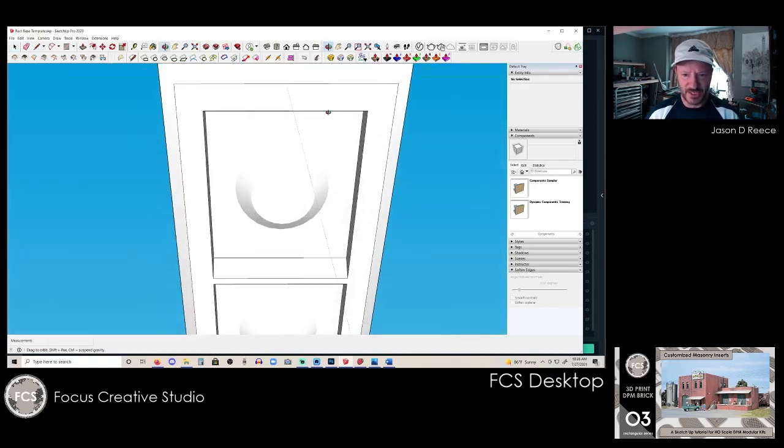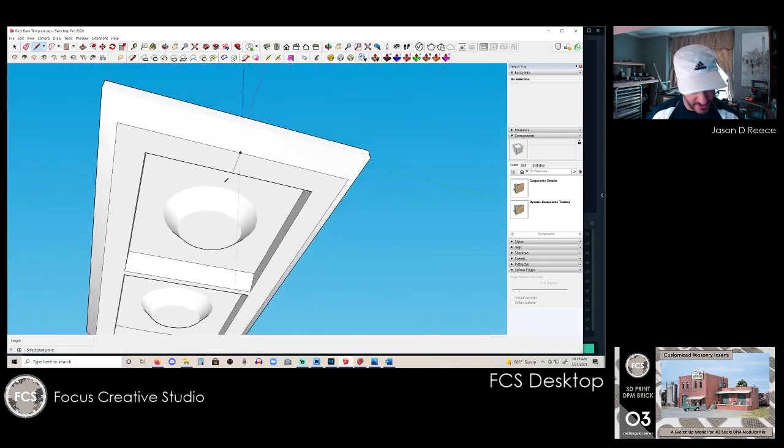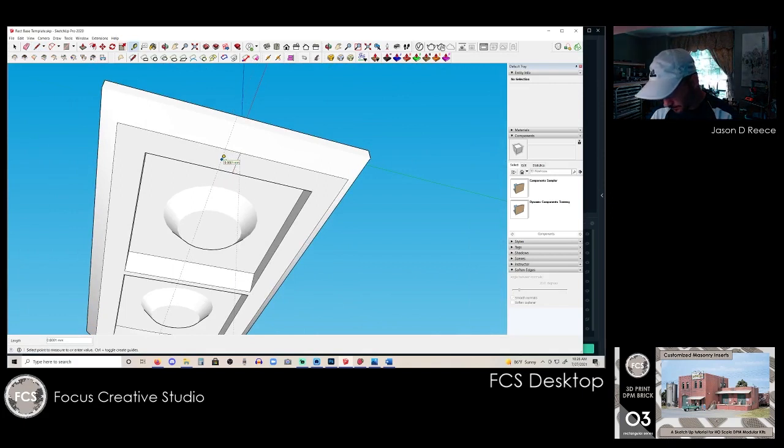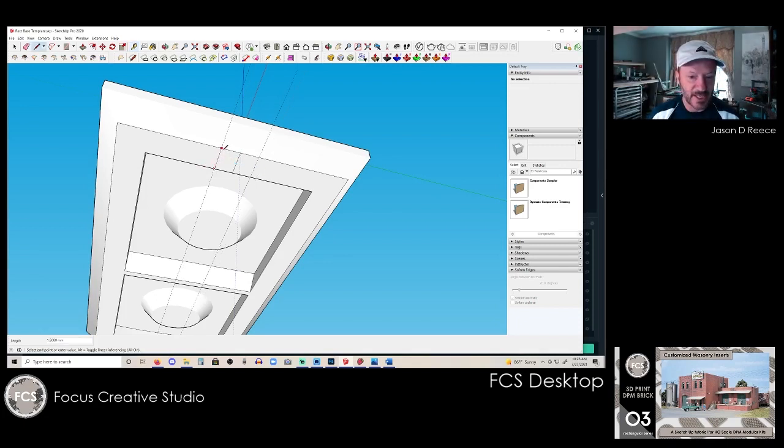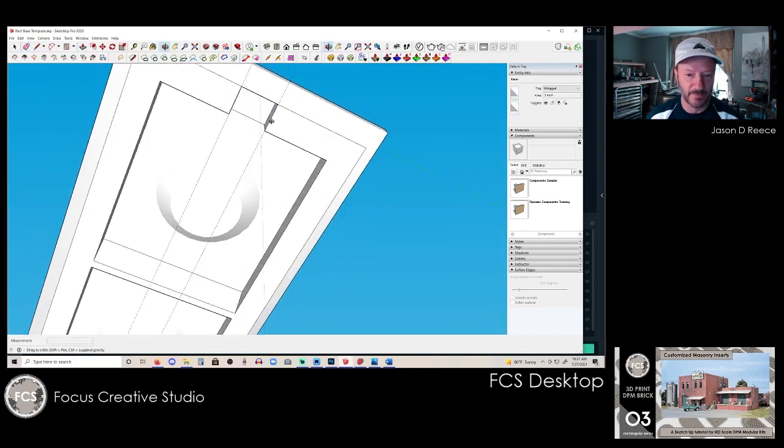So I've gotten into a habit of, with these models, also creating one just up here off the build plate. And this is really only because when it gets cold here, that resin isn't quite as viscous. And so those first initial layers, the resin can tend to pool. And so I give it a place to start draining in through the middle of this model immediately. So that way I'm hopefully not dealing with it. I'm just push pulling right down.